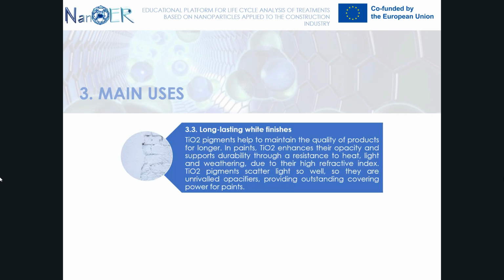Concerning long-lasting white finishes, TiO2 pigments help to maintain the quality of products for longer. In paints, TiO2 enhances their opacity and supports durability through a resistance to heat, light, and weathering, due to their high refractive index. TiO2 pigments scatter light so well that they are unrivaled opacifiers, providing outstanding covering power for paints.